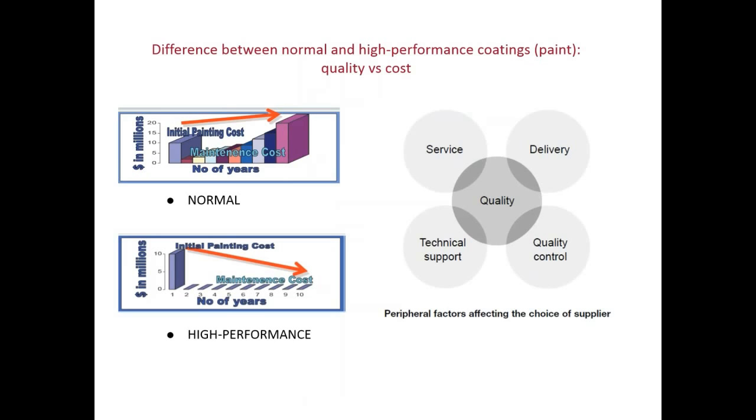On the other hand, some types of coatings are expensive indeed, but after the first application, very little maintenance is used. And so those two propositions are essentially a value proposition. A lot of people overlook the total cost of ownership, and this goes for both the metal, the structure, and as well as the coating.